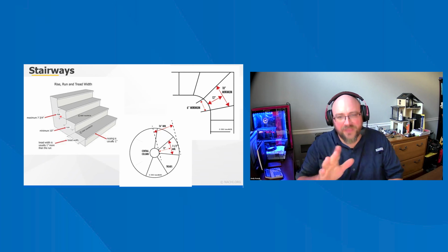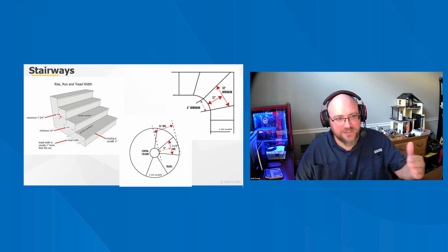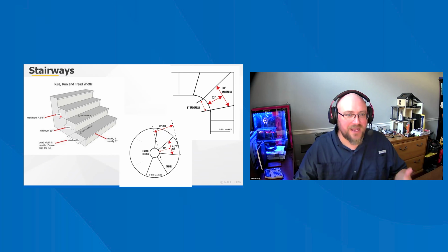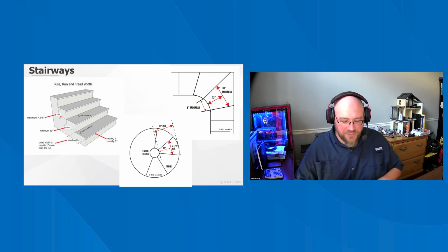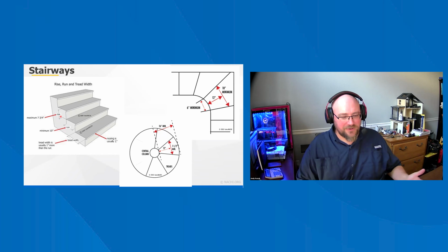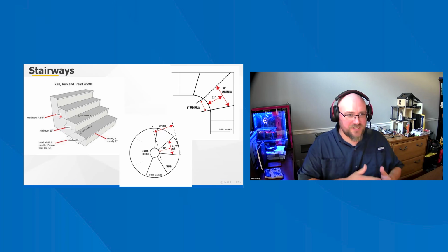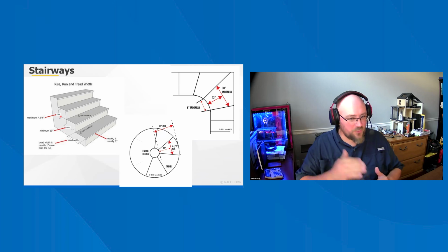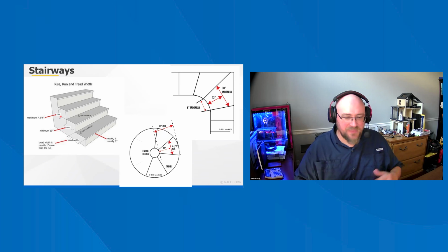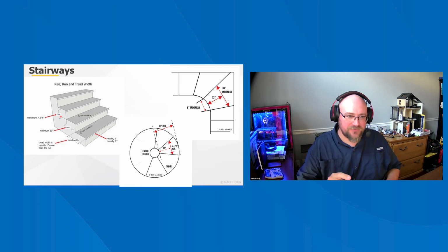The one thing I'm going to tell you about why having consistent rise, run, and widths of your steps is so important is a video I watched early on in my career. There were some subway stairs in New York, and every step was exactly the same, with no more than a 1/4 inch difference between each step, and people get in a cadence when they're going up and down steps. Then there was one step that I think was an inch taller than the rest.